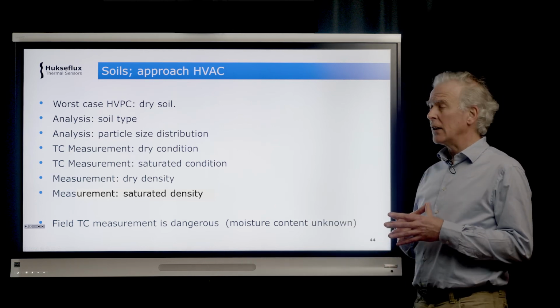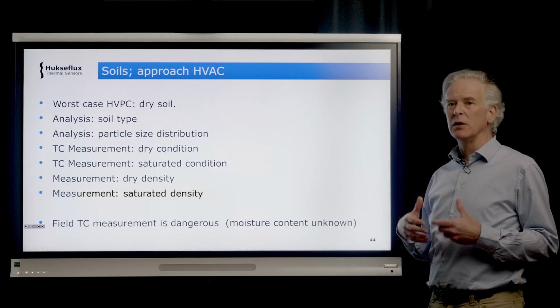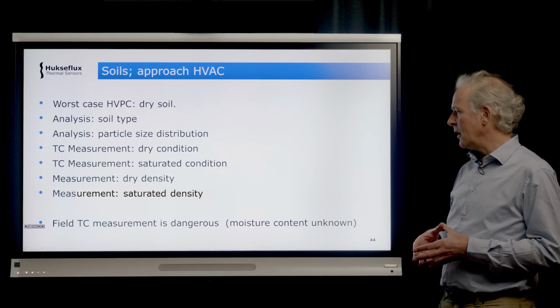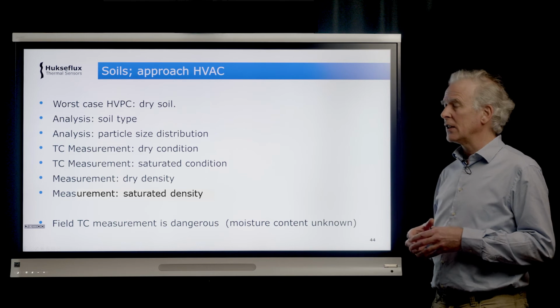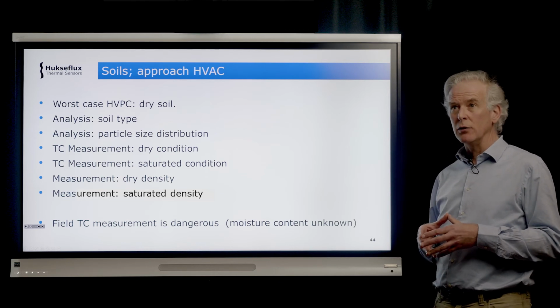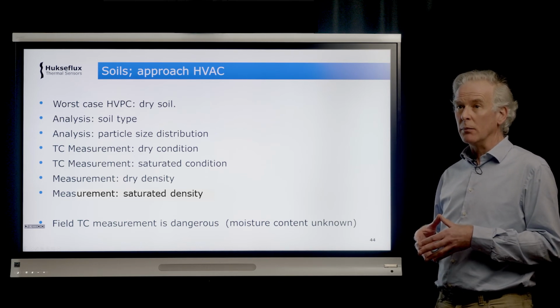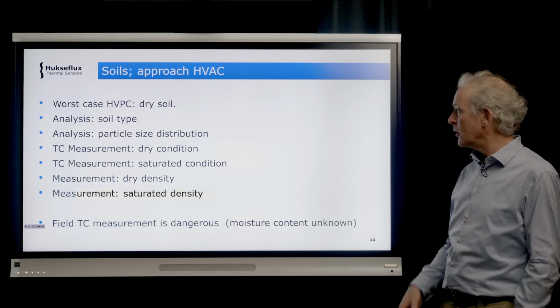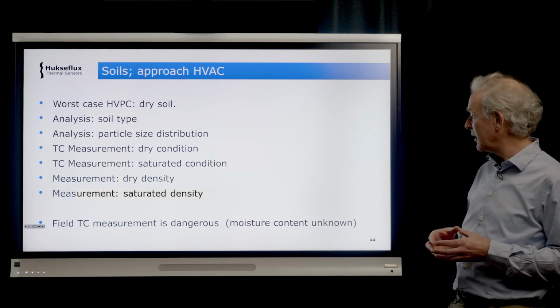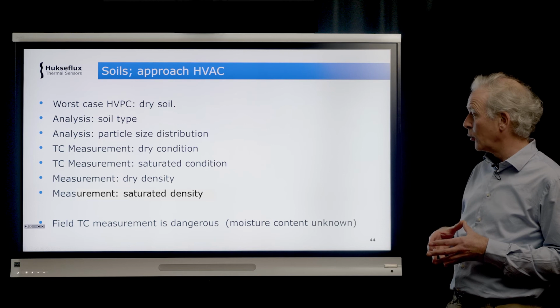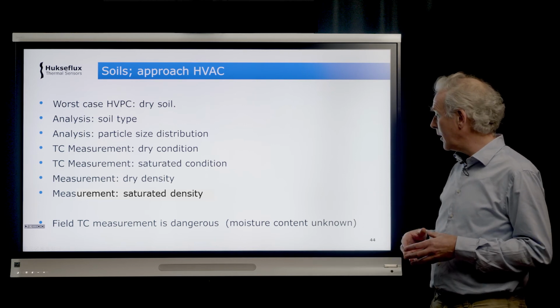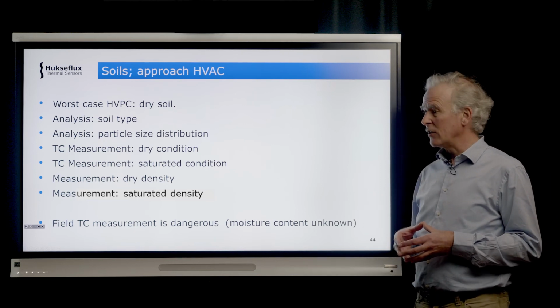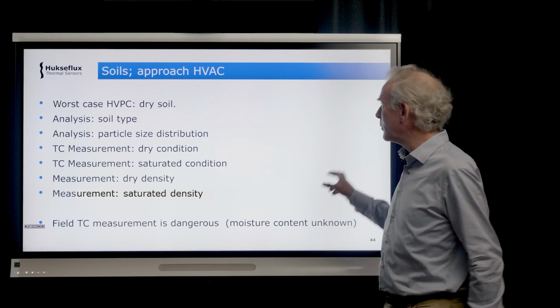What you should also realize is that if you perform a measurement in the field, in many ways that's a dangerous measurement, because you have no control over the moisture in the soil. We get back to that later, but moisture content is a variable that has a big influence on the soil thermal conductivity.